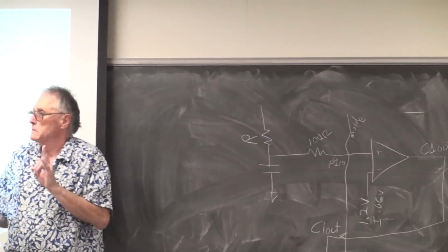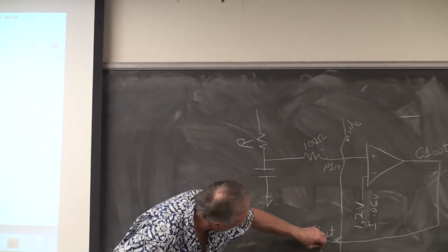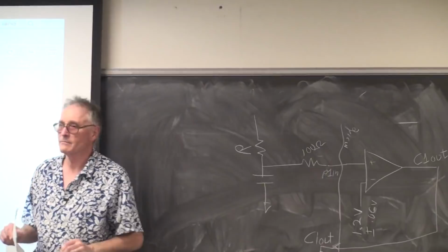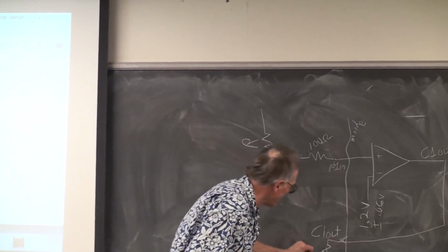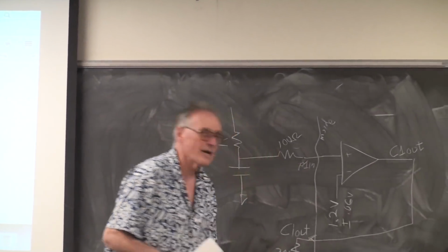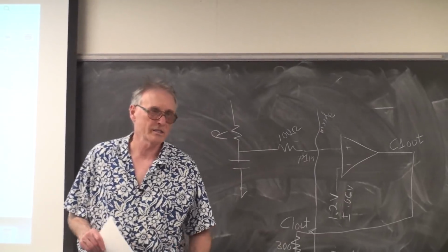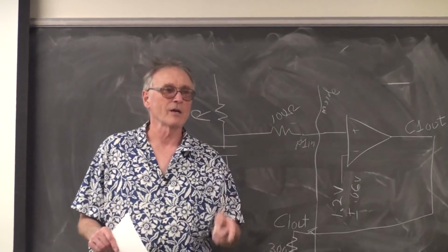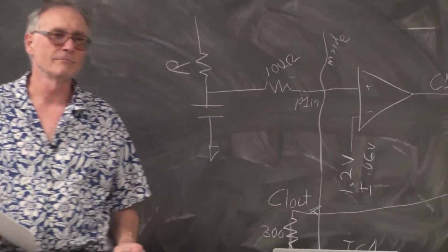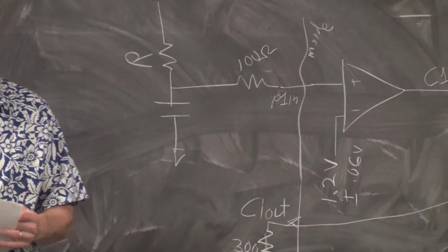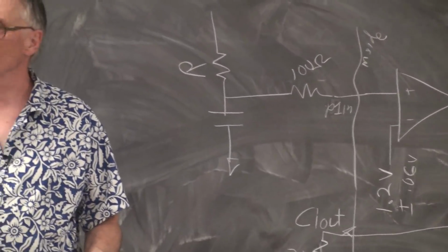Oh, resistor. Okay, 300 ohm resistor, because you never know. You set both of those to outputs, fire one high, one low, one's dead. Then you'll bring me the chip and I'll say, use channel 2.